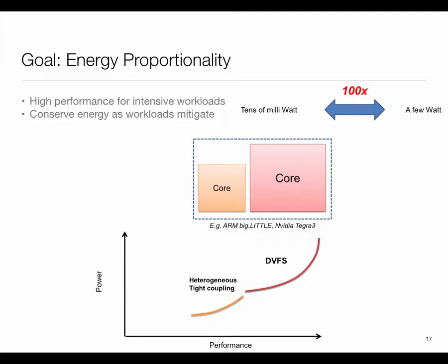These kinds of capabilities. So you often see two cores of the same instruction set put together in a very tight coupling. ARM calls this big.LITTLE. So a big processor and a little processor paired together. The idea is that through some intelligent software mechanisms, you can switch between one or the other, or use both as the case may be. When the system is in a mode where it just has to be vigilant, looking out for events, doing little stuff, perhaps you shut the big core and keep the little core active, and when something happens, you realize it's interesting and needs a lot of processing, you activate the big core.